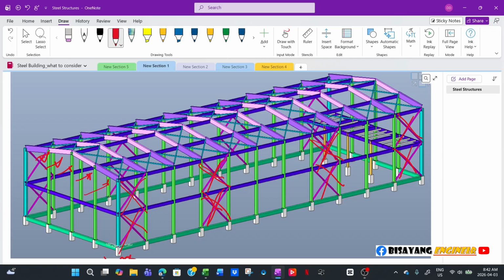Usually the tension rod that's used for cross bracing in metal buildings that I've worked with, where I designed the foundation and even the cross bracing, the tension rod for the steel buildings that I used to stamp, ranges from half inch, 5/8, to 1 inch diameter, and then it will optimize the capacity of that one.